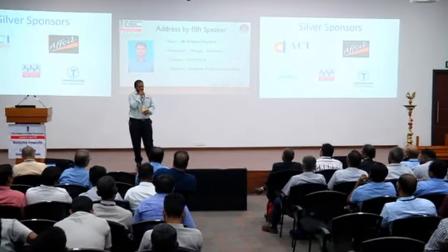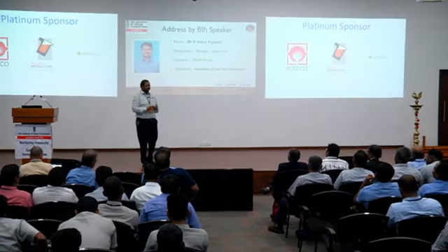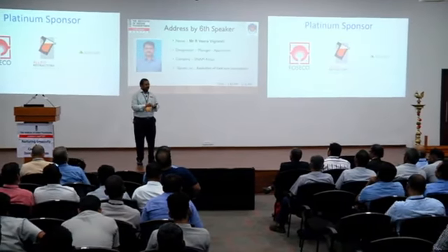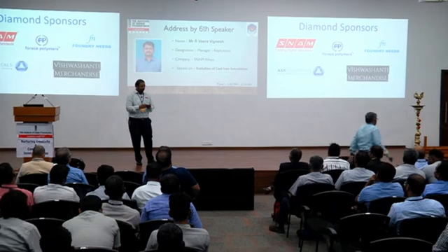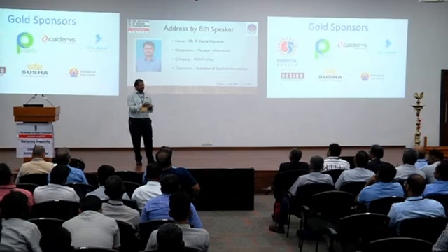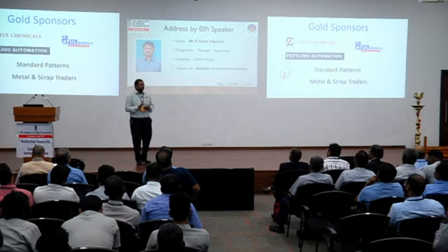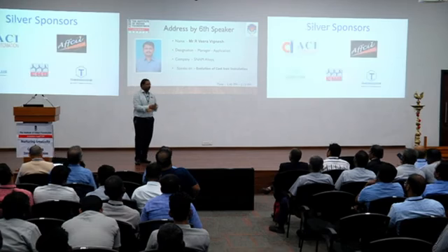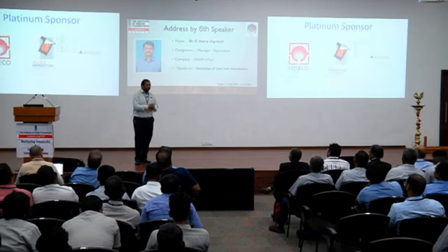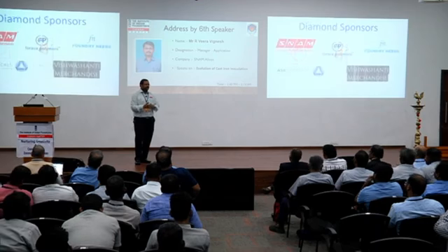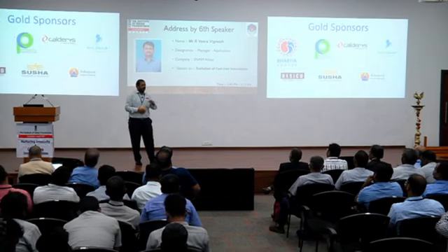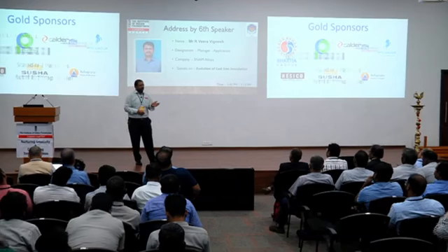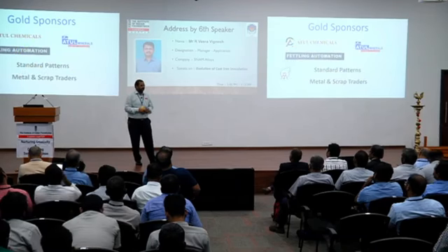Sir, in any inoculant, say for example the aluminum inoculant will have iron, silicon, calcium, aluminum. It can be other elements, or we need not have the other elements. If we have this four component system, the reactivity of your liquid metal and the oxidizing potential of these elements are to be looked into when I choose an inoculant. Say if I give you a barium inoculant, the amount of oxygen available in your metal or the characteristics of liquid metal might not be as compatible with barium's reactivity. So there are some people who require aluminum, because aluminum has an equal or stable oxidizing potential as that of calcium and barium.